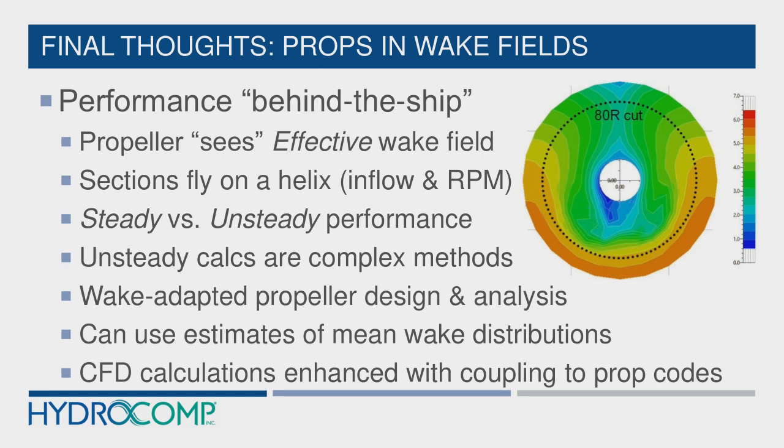And then prop elements is responsible for taking that total velocity, which includes the propeller effects, figuring out what those are, and then deducting it, subtracting it, to derive an effective wake field.